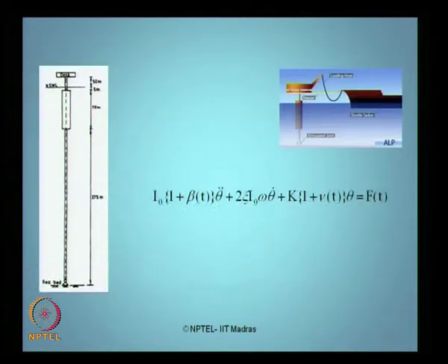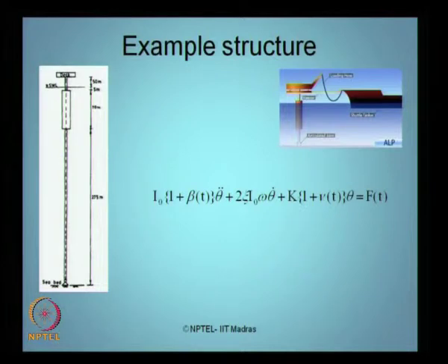So, what we do is we pick up a tower, as you see on the left hand side here, and you can see there are discretized points dividing this tower into various components. The height of the tower, the physical dimension, is about 275 meters, and the buoyancy tank is about 70 meters deep, located close to MSL, the still water level. Of course, the free board at which the deck is placed with respect to the still water level is about 50 meters, and the deck has all the conventional arrangements, which are not shown in this figure, but that will attract the aerodynamic loading on the structure.